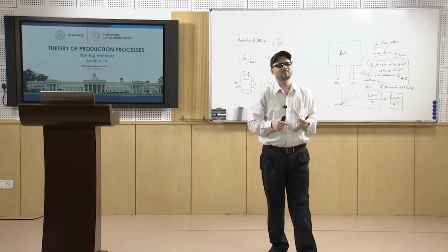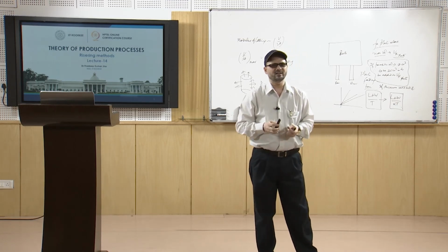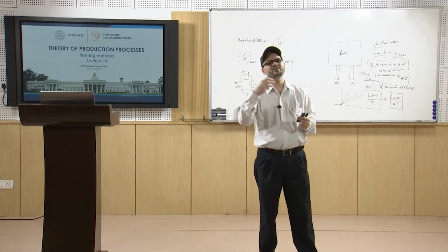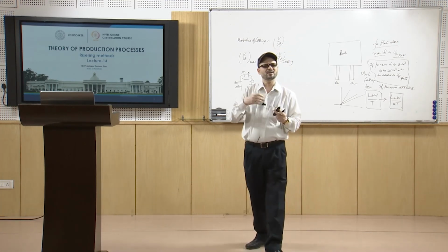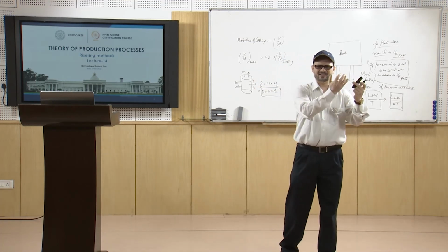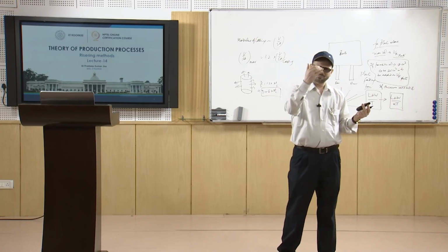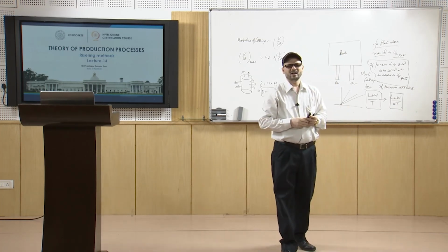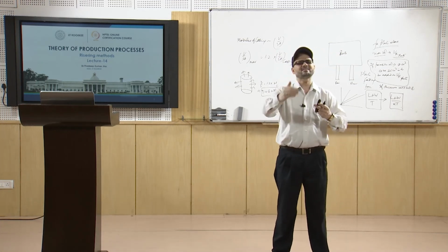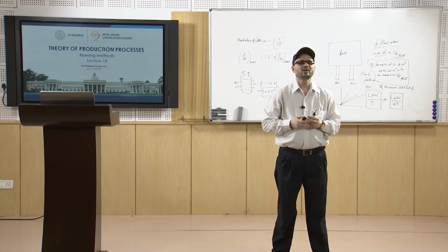This is normally used in wheel casting, for example crane wheel casting, where you use metallic padding. Or you can use exothermic materials and anti-piping compounds in the riser, so that the liquid metal stays for a longer time. By using these feeding aids the size of the riser can even be decreased, without the riser effectiveness being decreased. Thank you very much.